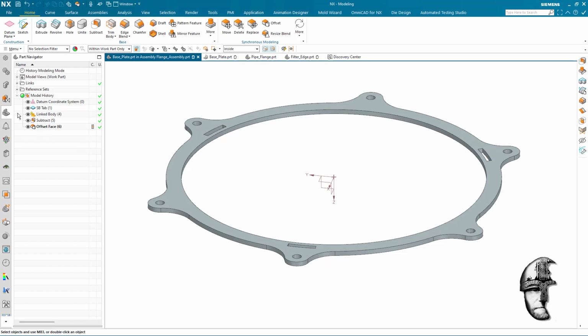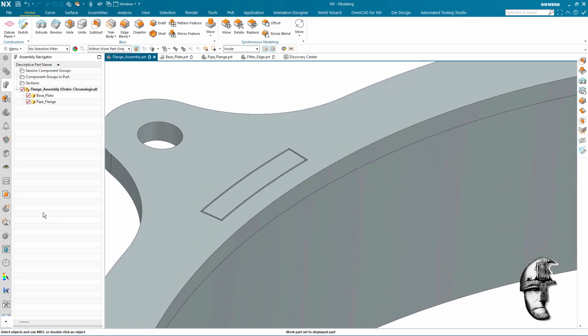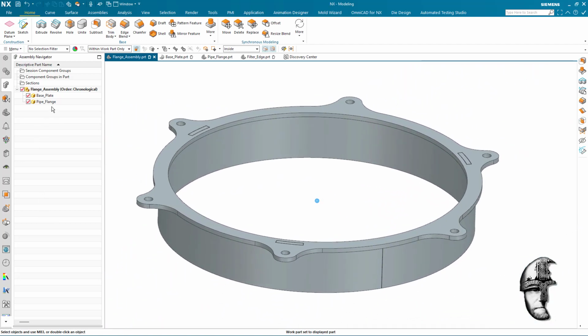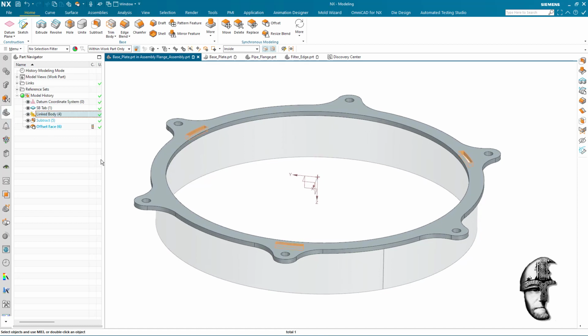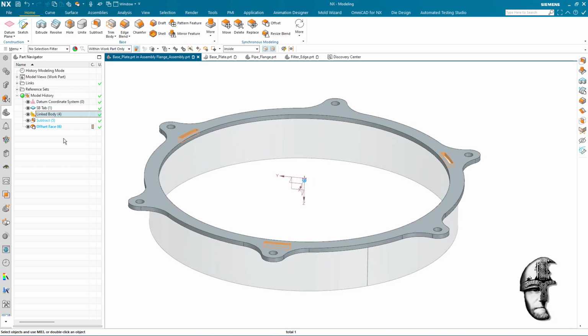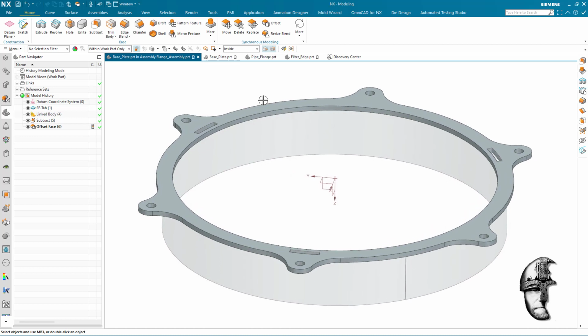And that will give us some clearance to the original there. Now to go back to see what that actually created in the base plate there, we can see that I created that linked body there, and that is kind of the secret. Pretty simple operation to do. And you can do it on the fly without doing the wavelink. Otherwise, you would have to do that separately ahead of doing the subtract. This does it in one go.